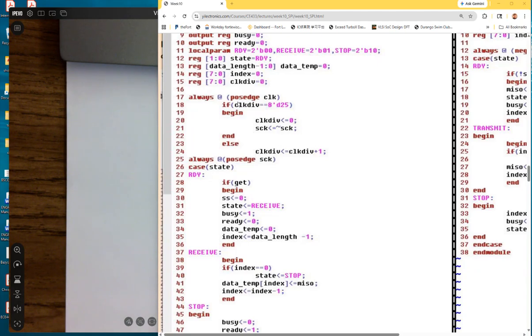Which means based on the frequency over here, whatever you design in the system for the communication, it runs 16 cycles to get one data out. So my question for you guys is, what's the sampling rate? I'm talking about samples per second, SPS, not BPS, right? SPS. And a lot of times you'll see papers with titles about an ADC design at a frequency of KSPS. What does that mean? KSPS.